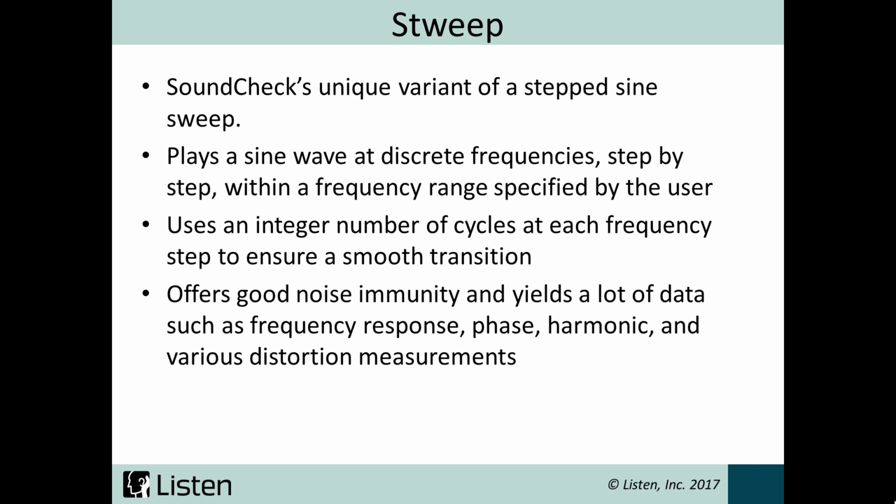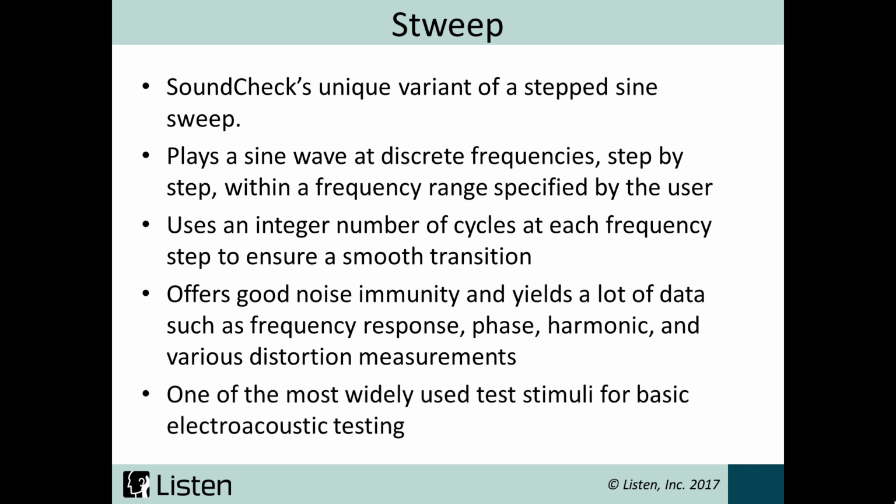The analysis yields data such as frequency response, phase, THD, and various distortion measurements. Sweep is one of the most widely used test stimuli for basic electroacoustic testing.